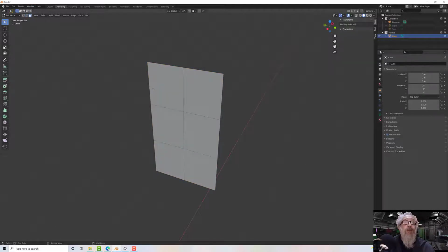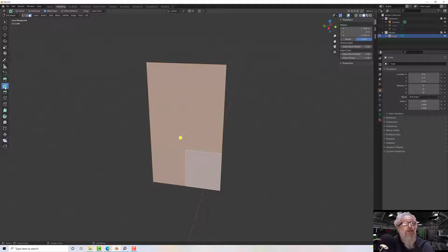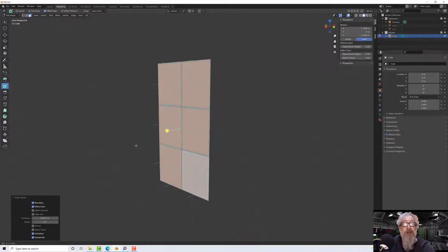So now in poly mode, I'm going to select each of our faces and use inset, but when I bring that in, it's going to inset everything as a whole, and I want it to do it on only particular pieces, on each piece individually rather. So down here in our options for inset faces, I've got individual, and now if I make that perhaps 0.5 inches, that will give me a nice little frame.